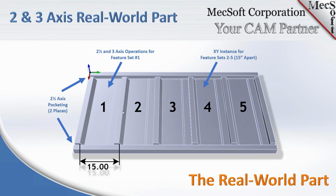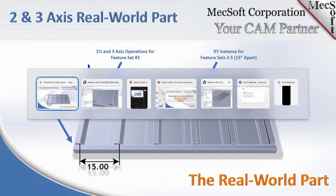So what we're going to be doing is programming one set, and then we're going to be using the XY instancing operation to automatically duplicate it for all the 4 remaining sets. That's why you see a dimension here, 15 inches between the sets. Okay, so let's hop right into actually programming this part.